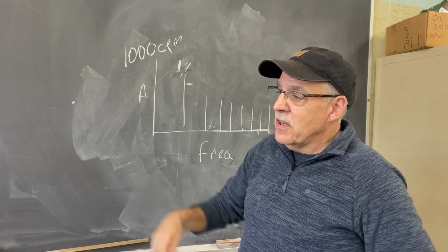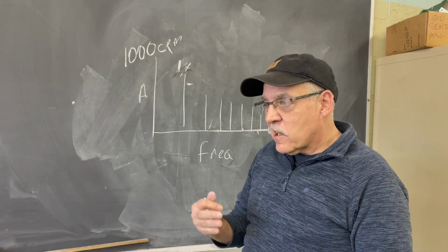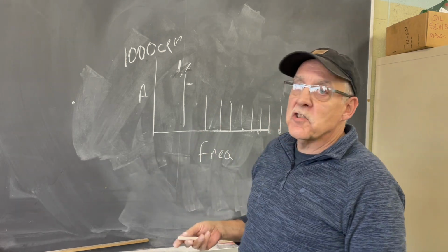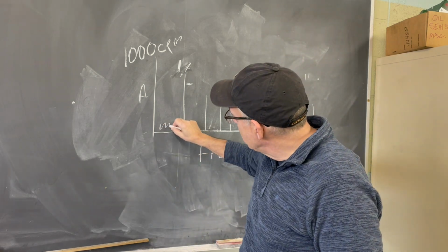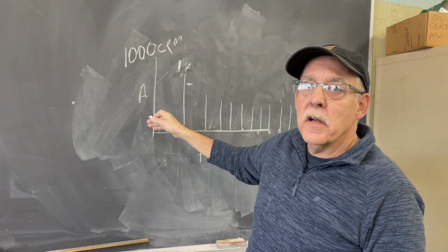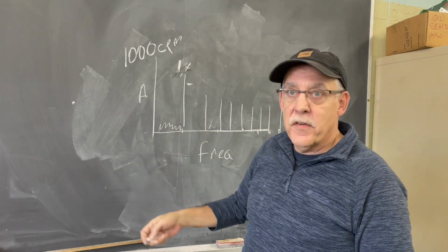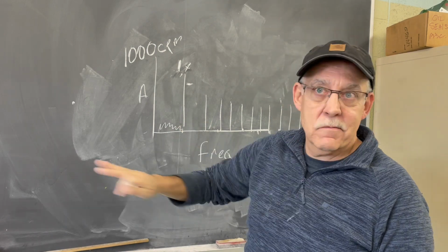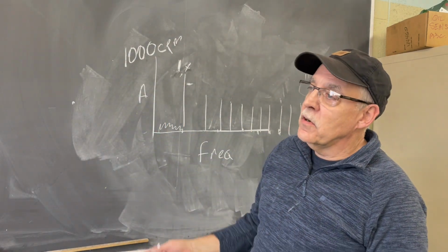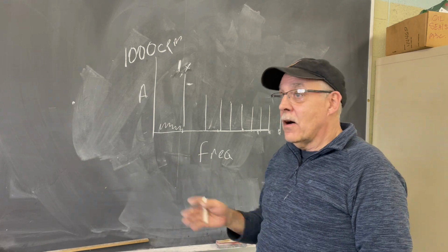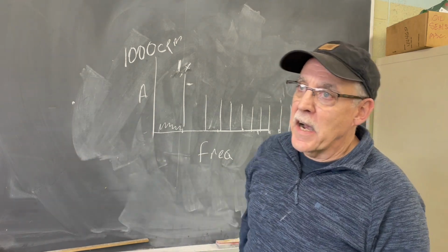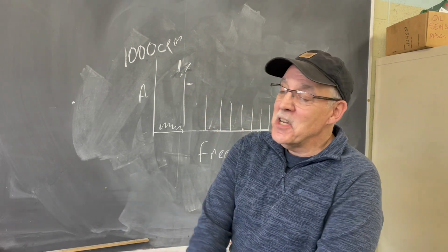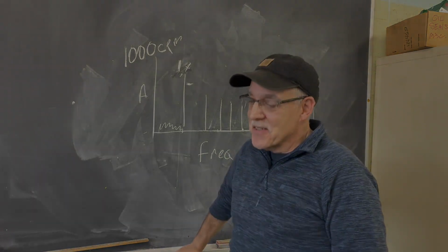Anything subsynchronous, like growling noise, you know, all that. Also subsynchronous vibration with the bearing. In the last stages of vibration, what you'll see is a lot of noise down below 1 times of the bearing. That just means that you've basically lost your fit, you've lost your clearances. That bearing is just getting ready to fail, it's at the very last stages. So subharmonics and harmonics all tell us about how long a bearing will last. And you don't learn that overnight, I can tell you that. It takes a while. You've got to look at a lot of spectrums to get that stuff down.